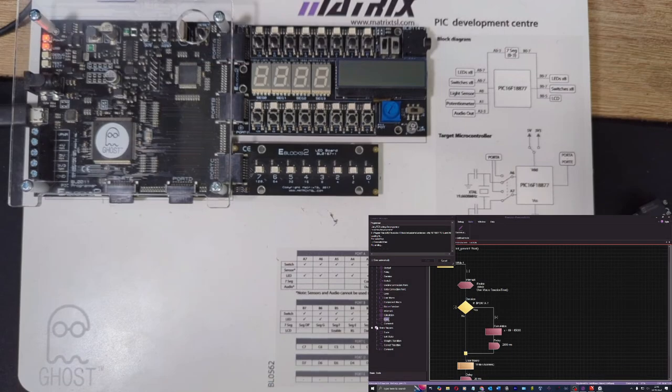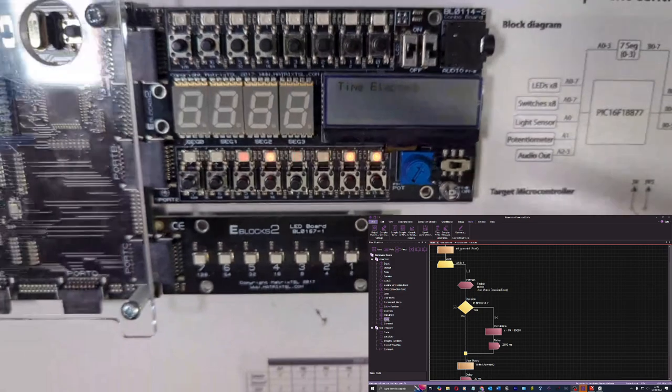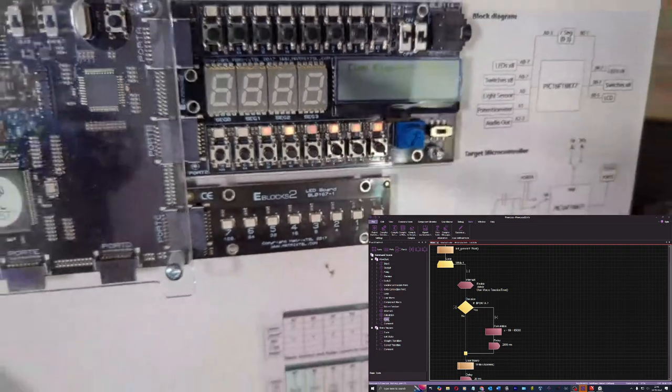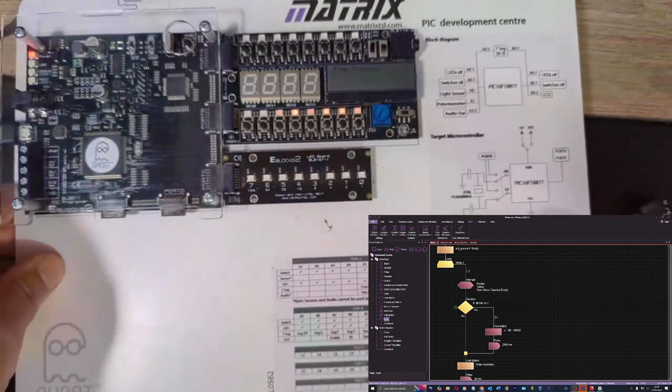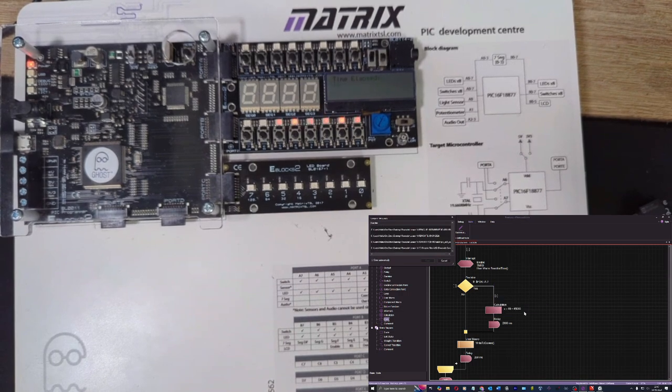So we download and have a look. Let's see if anything happens this time. So now in my timer interrupt, all I'm doing is incrementing. Oh, we're writing to the screen. So these LEDs are going nuts, which means it's writing to the screen way too much. So that's probably causing me an issue. So let's just fix that. We currently got write to the screen with a 20 millisecond delay. Let's go with a 250 millisecond delay. And then just try that again.